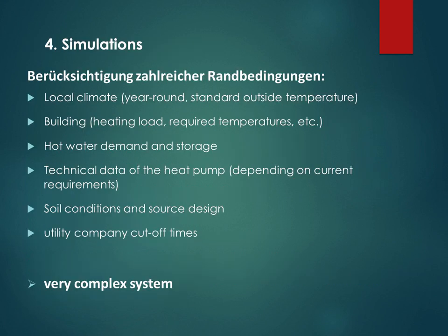I've demonstrated that numerous boundary conditions play a role in heat pump systems, including local climate conditions year-round, building characteristics such as heating load and required temperatures, hot water demand, and storage requirements, technical data of the heat pump depending on current requirements, soil conditions and source design, and utility company cutoff times. It is indeed a very complex system requiring comprehensive analysis.